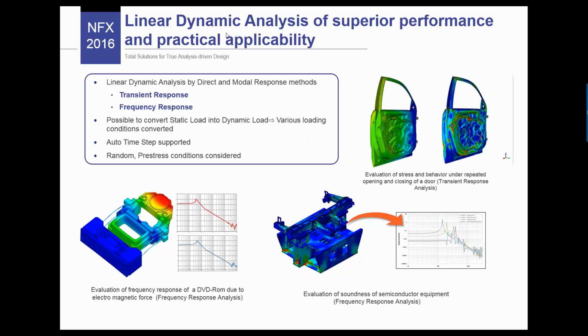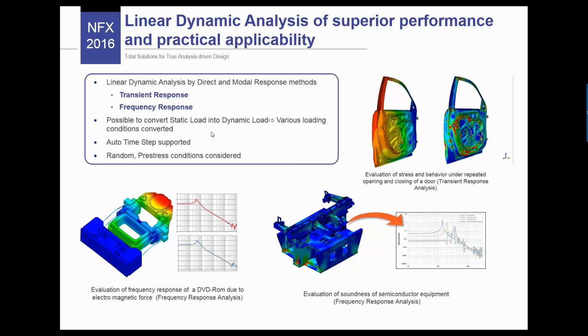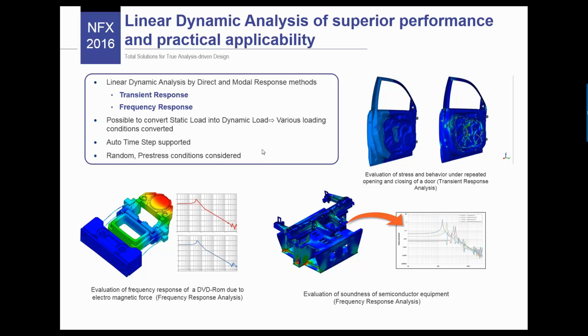You have linear dynamic analysis as well, both transient response, so time response, or frequency response. You can convert static load into dynamic loading, for example. You have also random analysis, or you can consider pre-stress conditions.